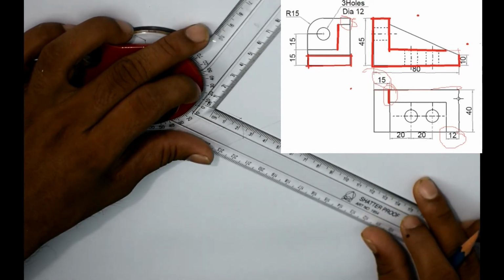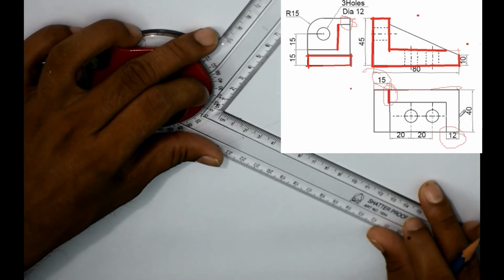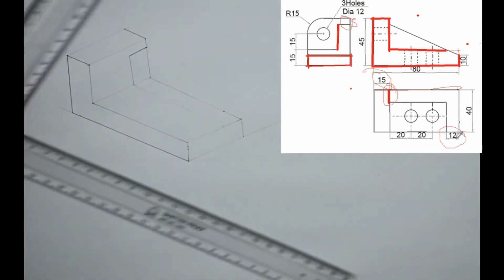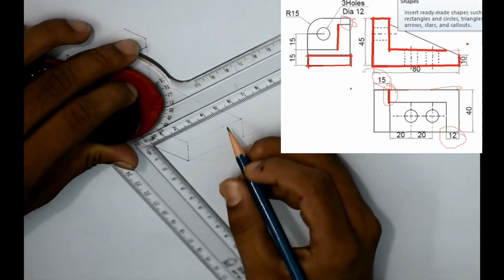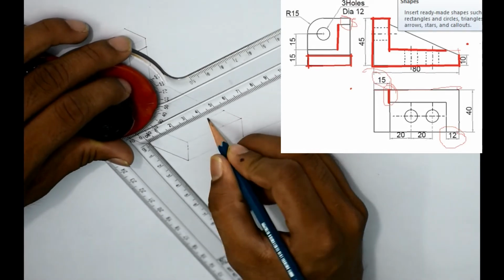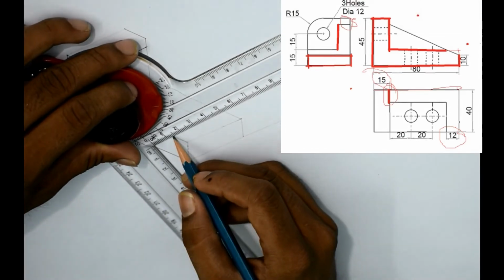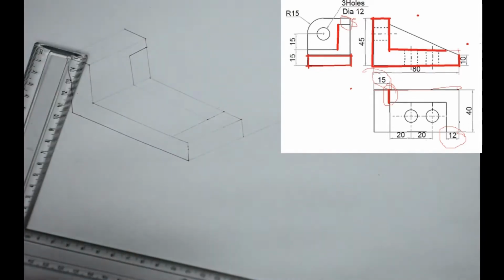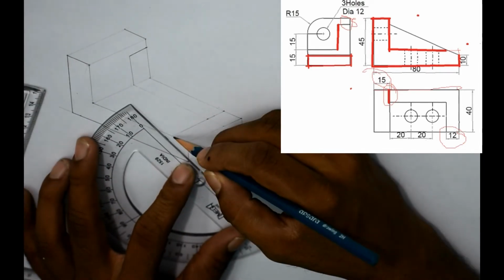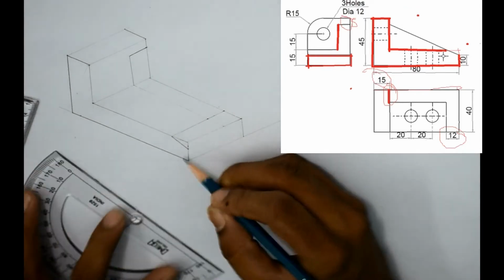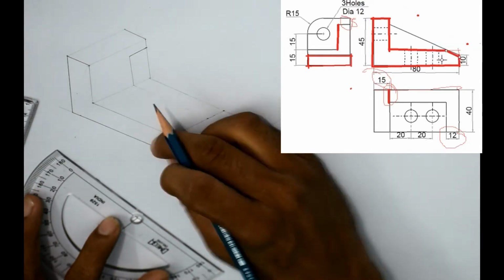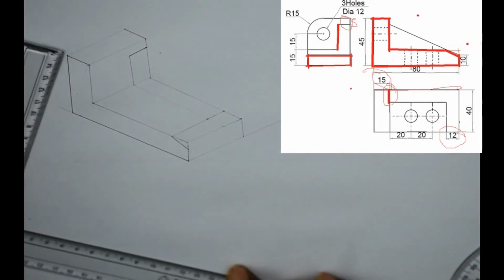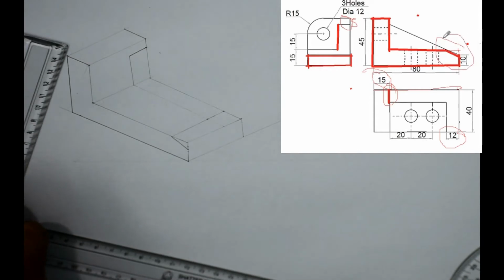See this in the top view also. So this is 12 mm. In the front view there is a curved portion here, which will now be formed easily by joining these 2 points. This is the 10 mm distance line and this is 12 mm from here. Now to avoid ambiguity, I will erase the extra lines, but first I will complete this rectangle.